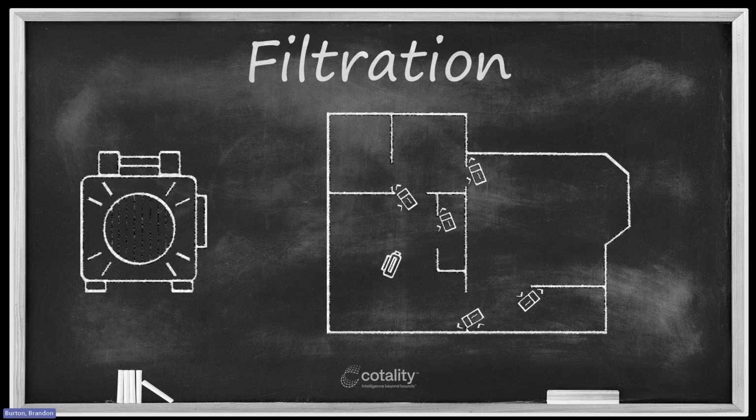So with that in mind, I tend to lean on putting my air scrubbers more out towards the center of the room once I'm in an active drying process. Okay. But the nice thing is it doesn't really matter where you put it because you've got good circulation. And if you don't have good circulation, fix that. Then it won't matter where you put it. All right. So with that said, that's air filtration.